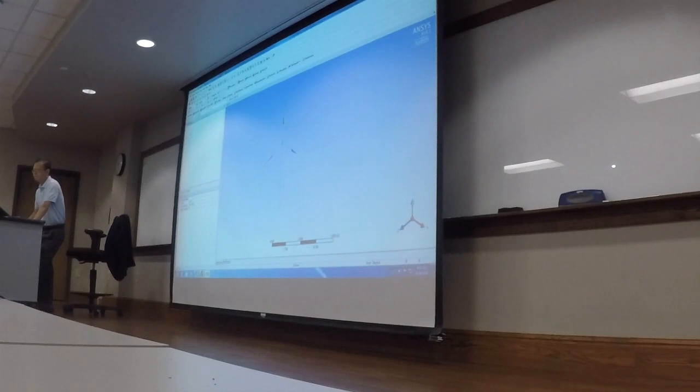Sketching, settings, grid, check, major grid spacing, 1 inch, minor steps per major, let's use 2. All right, so we'll have a very nice grid here. And go to draw.